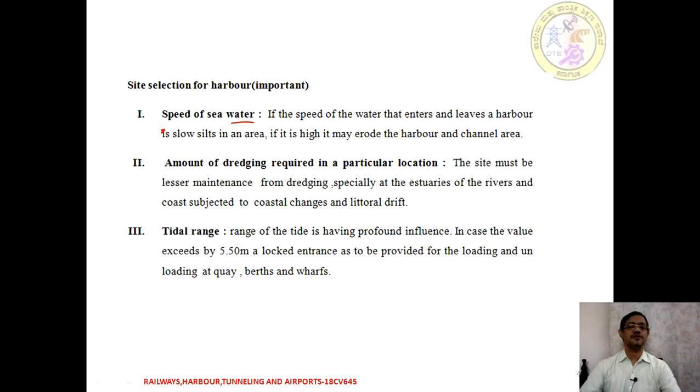After that, the amount of dredging required in a particular area. As we know, the minimum draft has to be maintained. From that aspect the site must require less maintenance dredging, and especially the estuaries are a concern, where the site is subjected to coastal changes and lateral drift.